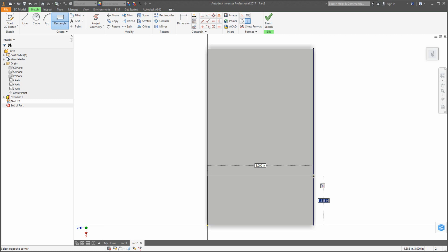Those of you who might have been exposed to older CAD systems where they didn't have constraints, you used to have to use all these drawing techniques and tricks to get things to line up. Now with these constraints, it makes your life a lot easier. So anyhow, let's go ahead and snap to this area here. You could, I guess, type in 1.5 for the height and then snap to that area.